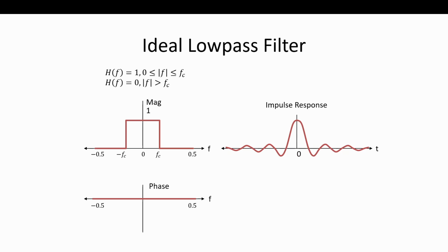That's right. It's the same phase shift across different frequency components. And there's something special about it. The zero phase filter has absolutely no delay. So really good, and a really good takeaway is phase. I said, pay attention to phase. Even for us, a fixed delay in time looks like that in frequency for its phase.